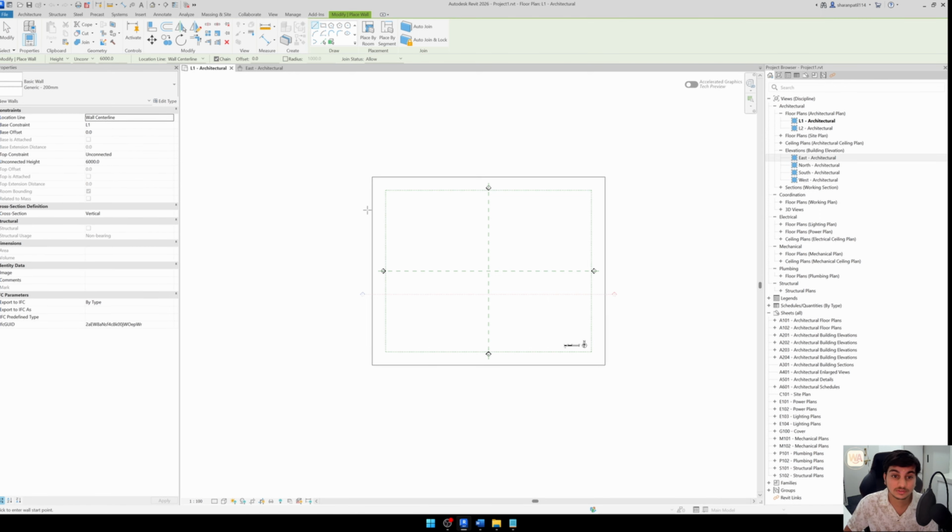When you click on wall architectural, you can see to the left of the screen there is a properties box which is indicating a wall of generic 200 mm, right? Just see everything, like what is the base constraint? Suppose imagine you have a building, this is your top constraint and below is your base constraint. The base constraint will be at your ground line, right?